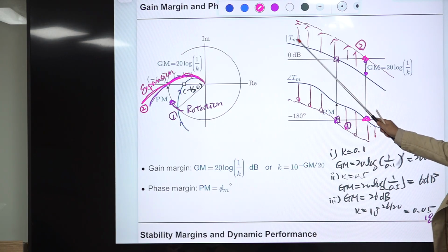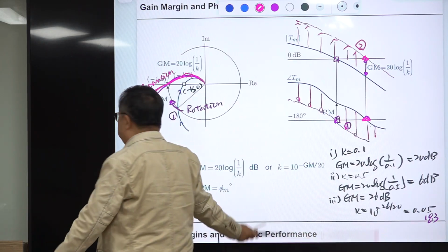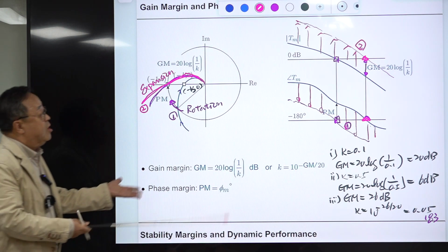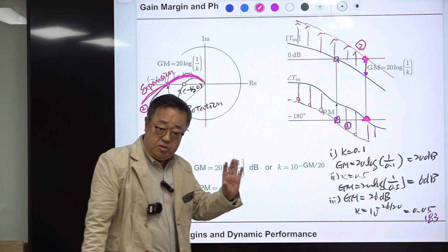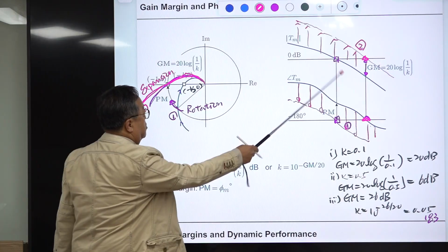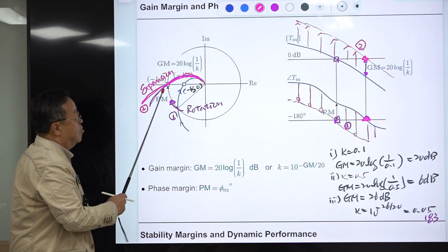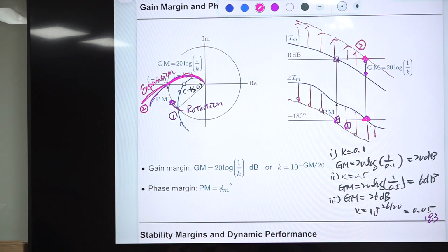So if you see this from your measurement or simulation, then you can directly evaluate the phase margin and the gain margin. If you want, you can write a simple program or a simple spreadsheet to transfer this to this, and from this you can read out these two margins, which is the same as this one.